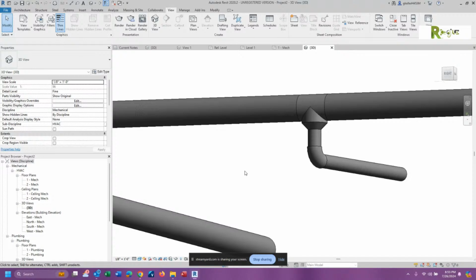Try to draw a bathroom. Draw a riser. Show me what you know about risers. You got the sanitary line, but then we've got a vent line that comes off of there. You got a domestic hot and domestic cold. The hot would go over to the hot water heater, and the cold would probably go somewhere in the corner of your building where you're going to connect into the main. That makes sense? Yeah. Oh, good.